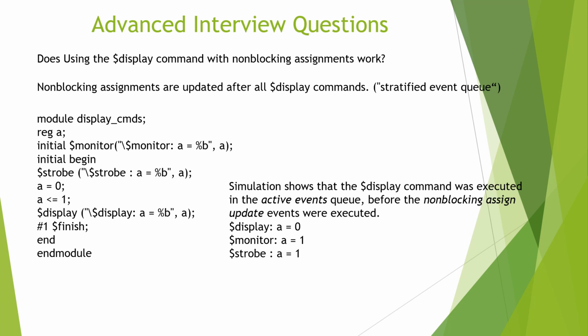our previous slide we remember that the $monitor will be executed at the end, so $monitor will get executed after the assignment of non-blocking 1 to a, so it will report a as 1. Similarly, $strobe will also report a as 1. So this is a typical example where you can see the Verilog stratified events queue taking effect.